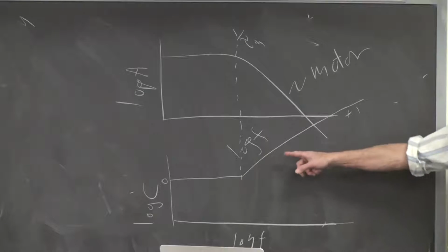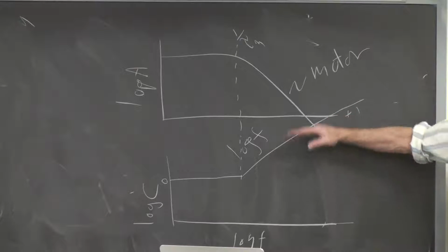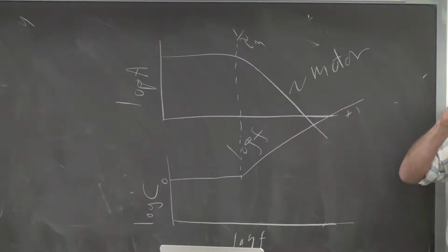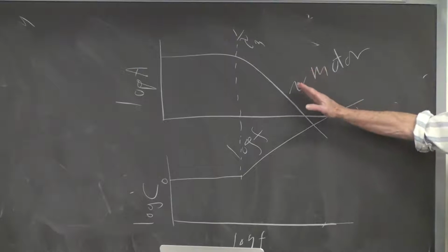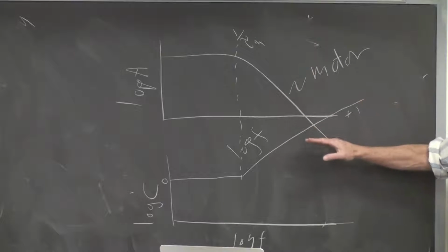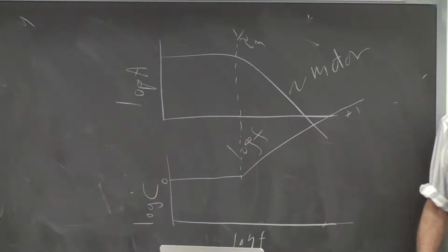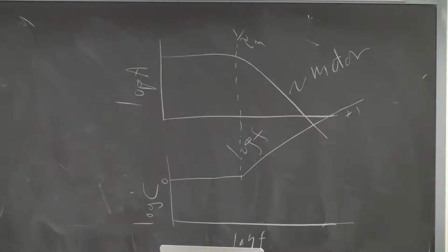Now, if we multiply these together, on a log scale, if we multiply a slope of -2 times a slope of +1, we get a slope of -1. So now the slope is -1, the phase shift is -90 degrees, everything's stable.